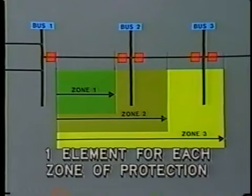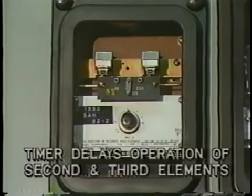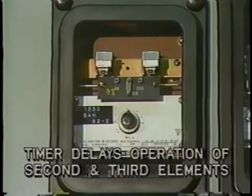Usually, a second element is installed to protect the remainder of the line and reach out into the second zone. A third element may be added to reach even further, and so provide backup protection for the first and second zones. In each case, a timer is added so as to delay operation of the second and third elements in order to allow the primary protection to operate in those zones.